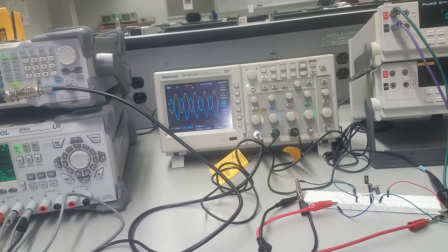That's what the specs of the circuit were. Then we realized the gain was higher than the range, so we said we need to lower the gain. One way to lower the gain is by decreasing the current, and we can decrease the current by increasing RS.